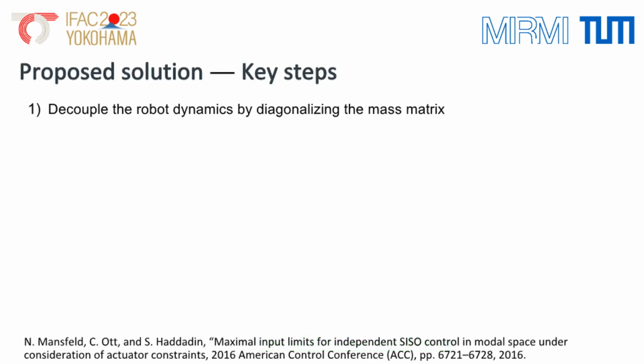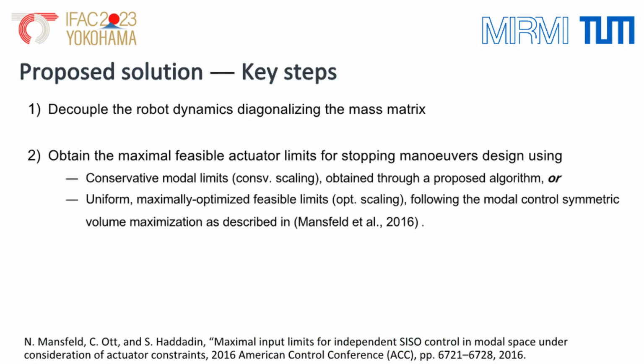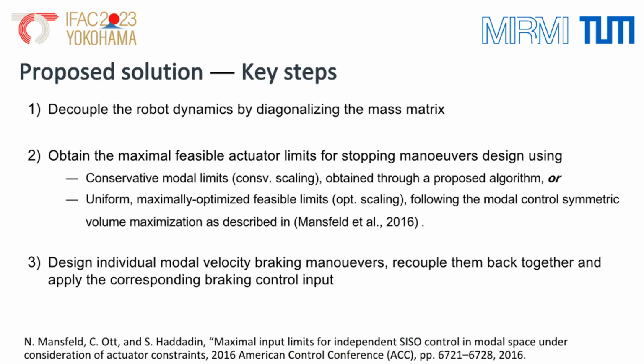The key steps of our predictable braking framework are the following: decoupling the dynamics and transforming joint velocities at braking instant into the modal space. Then, obtaining the maximal feasible actuator limits for the modal coordinates. Followed by designing the individual, decoupled stopping maneuvers geometrically using Bézier curves under these limits, and finally recoupling and applying them for control in the original input space.